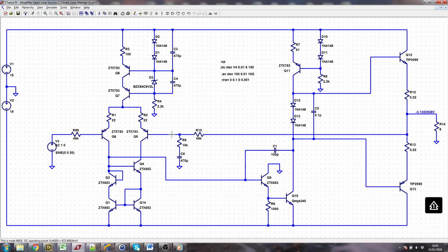Could be that I've made these a little bit big, and this current has to produce a big voltage across here, and that's pushing the offset. But I suspect it's got more to do with our dodgy biasing scheme. So we can try to adjust our biasing arrangement. First thing I'll do is just delete the feedback line because it's in the way. Then I'll try and make the output stage look a bit neater. Maybe we can try to pull this one down a bit.